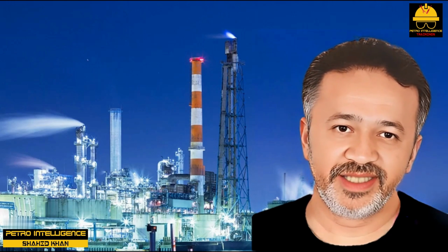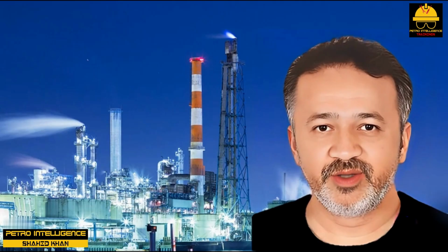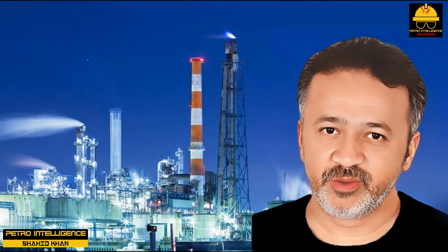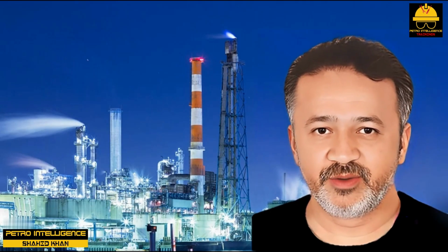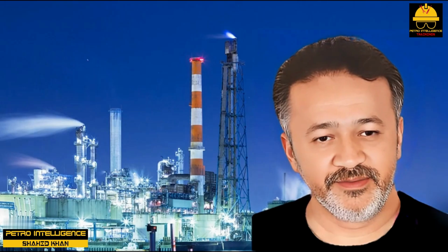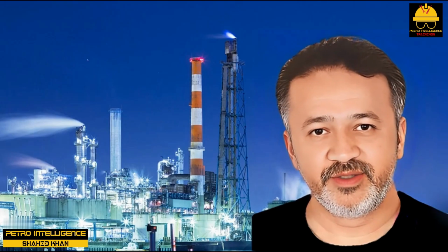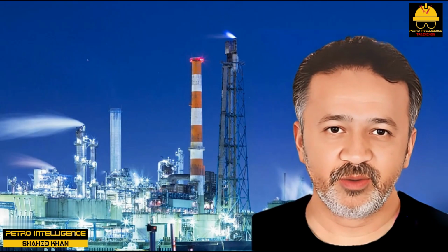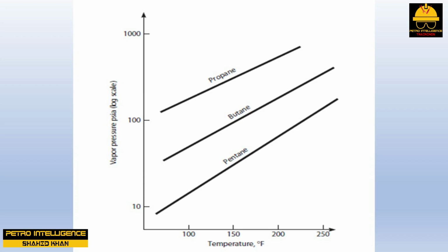Many of the tubes in the condenser would be submerged in the liquid refrigerant. The refrigerant would be subcooled below its condensation or bubble point temperature. It would have to be subcooled, so that after the liquid lost 10 psi of pressure it would not flash. To subcool isobutane so as to prevent it from vaporizing after losing 10 psi, the isobutane vapor pressure must be reduced by 10 psi. This would, in turn, require cooling the isobutane by about 5 degrees Fahrenheit, shown in picture.